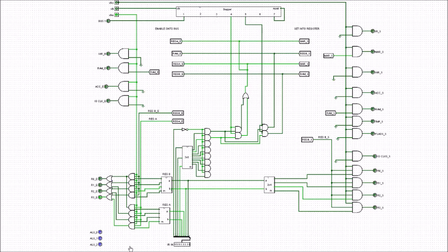So you see here that there's a couple of sections we're actually taking out because we're not going to use them here. They will be in the final version of the control section, but they're just going to clutter this up. So for example, we're taking out the section here on the opcodes to the ALU and a compare section here as well. So we don't need to bother with that, we'll just leave them out just now. But you see here we've added in this extra little section, and you can see it's a 3x8 decoder.